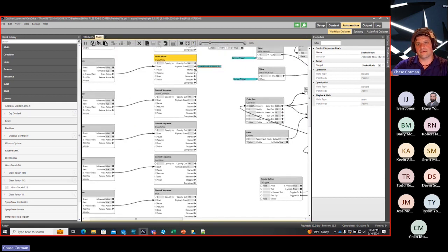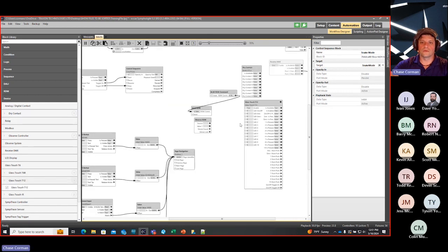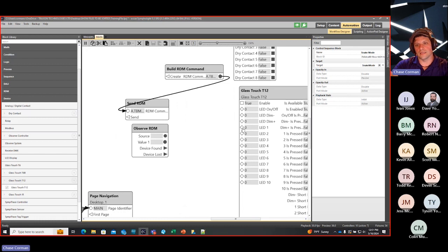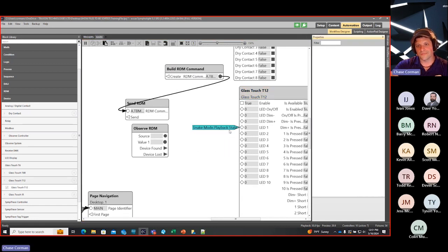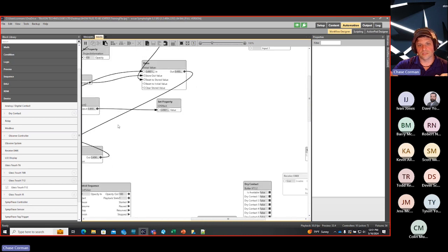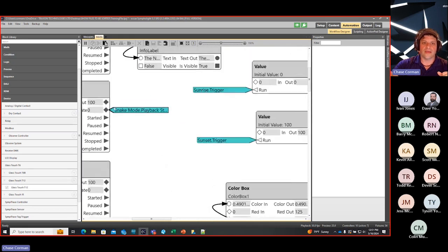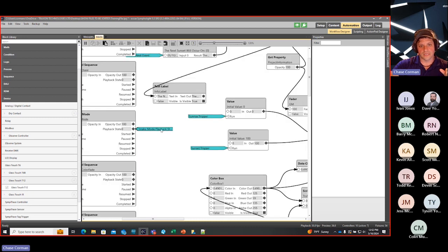So I'm going to connect that playback state to my LED 1. You'll notice I can only connect things that are outputting this data type. So I'll double click here. Now, I think I mentioned this yesterday, but we'll continue to mention it so you can get this in your head: that orange or reddish band that was around this is now gone. The reason for that is because this flag has actually been connected somewhere. And if I click on it once and leave my mouse hovered over it, you will now see a little bit of information here.